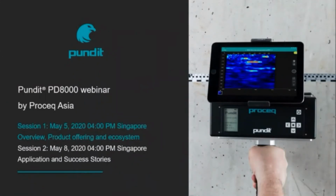And this is actually something you can only detect with Pulse-Echo. GPR would be blind to that. Cracks going down vertically from the surface, this we can't detect. But if they're more or less parallel to the surface, then we can detect it.